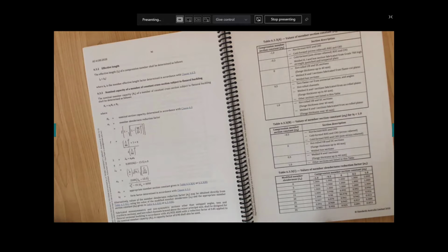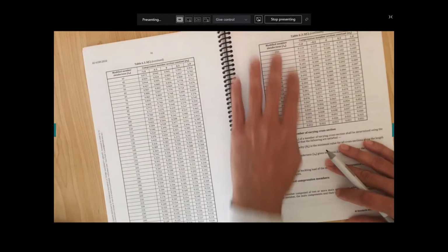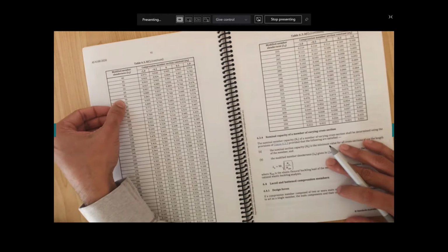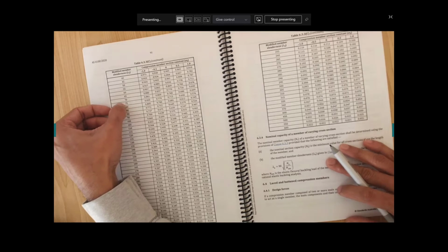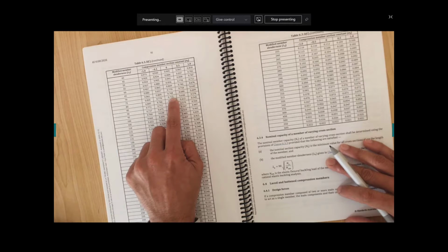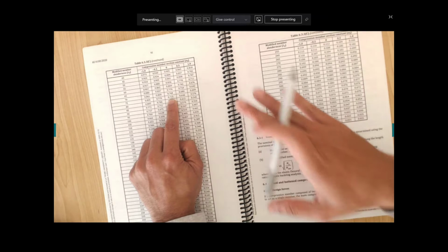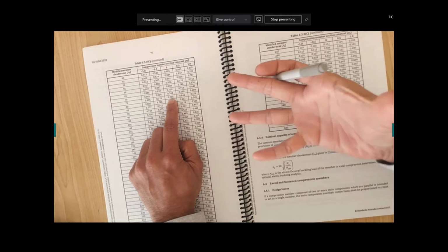Now we're going to identify whether our column is short or long by putting in 74.4. Look, these new standards, I don't like it. They break these tables into 2 pages. In the old standards, we had it very nicely on only 1 page, but that's how they decided, by the way. So you have 74.4, so almost 75. You can do interpolation if you have an intermediate value, and alpha b value 0. We just got it. At 75, you have 0.715. Almost 30% penalty has been given to you on the column because you have global buckling, because you have a long column, 3.5 meter column.